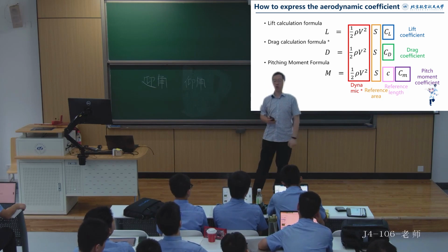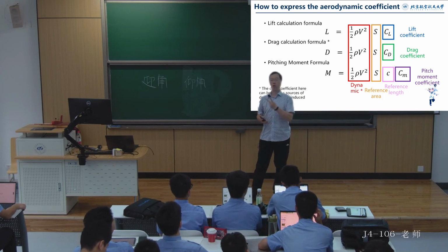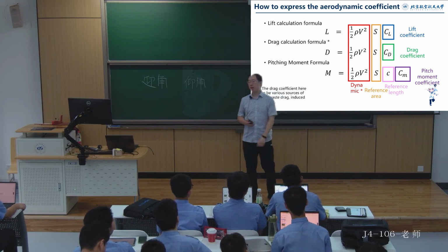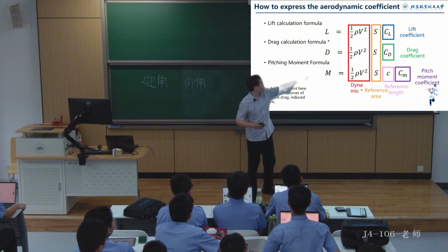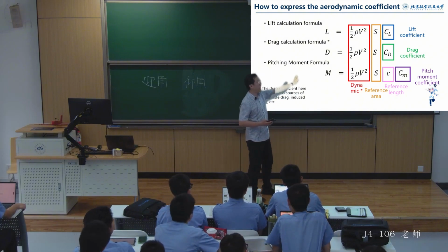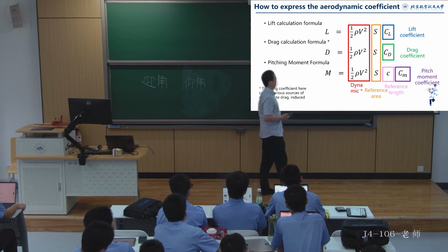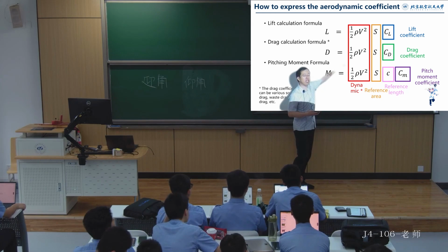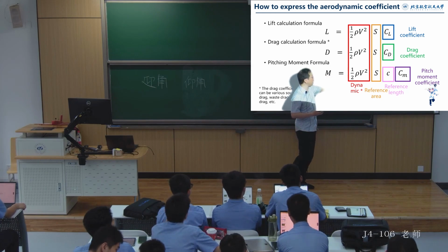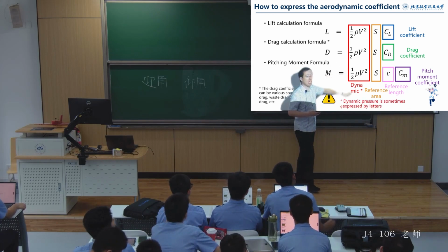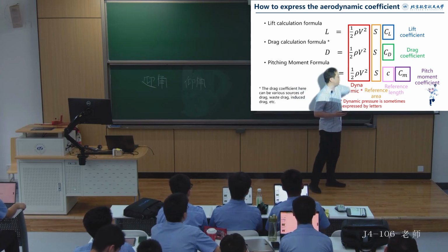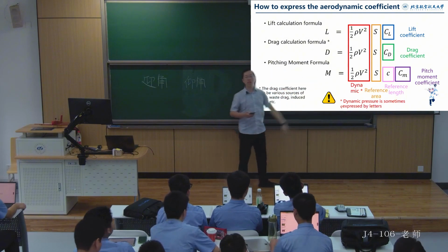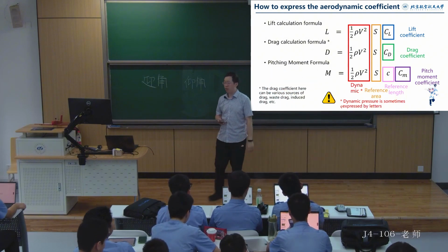that is, the same effects, so it's the same side slip angle, and when the Reynolds number and Mach number are similar, at this point, we can use the same coefficients and directly apply them to the full-scale aircraft. This is done by incorporating the actual flight environment's dynamic pressure when the full-scale aircraft is flying. The dynamic pressure resulting from its flight speed and altitude, combined with the reference area and reference length of the full-scale aircraft, allows us to obtain the conditions when the full-scale aircraft is flying.